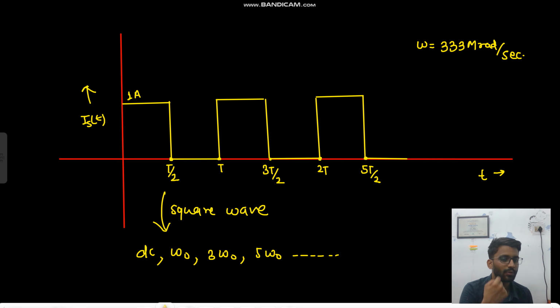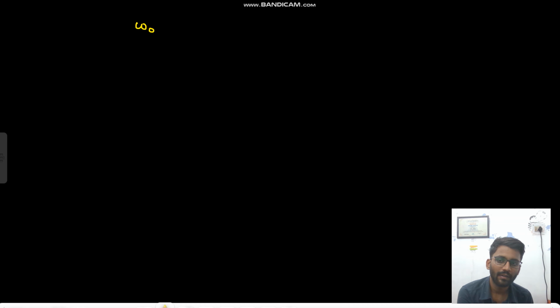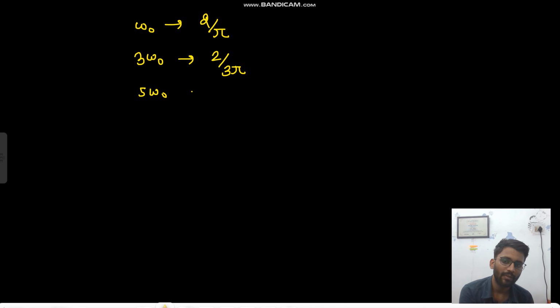And also I told you to remember the magnitude. So what is the magnitude? Magnitude is 2a by n pi. So here, 2a is 1 ampere, so it is 1 by n pi. Okay. So for omega naught it will be 2 by pi. For 3 omega naught it will be 2 by 3 pi. For 5 omega naught it will be 2 by 5 pi.